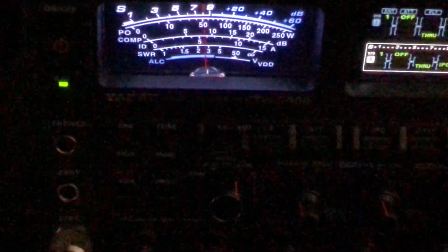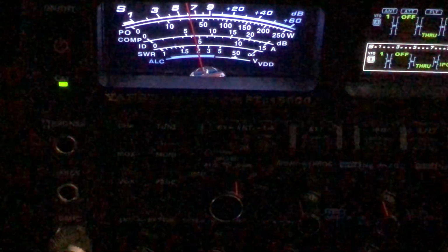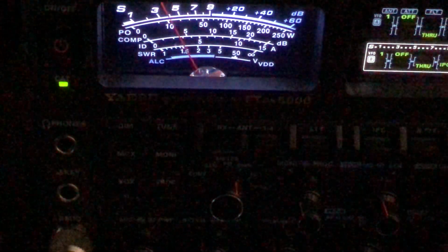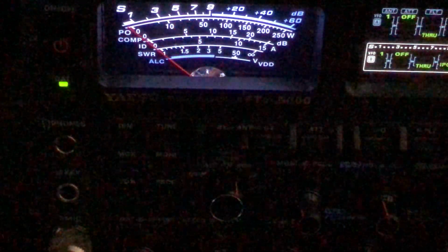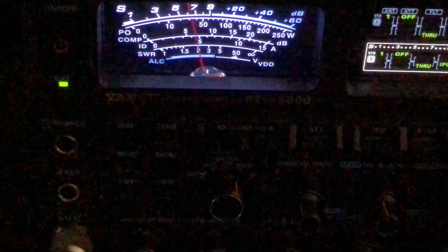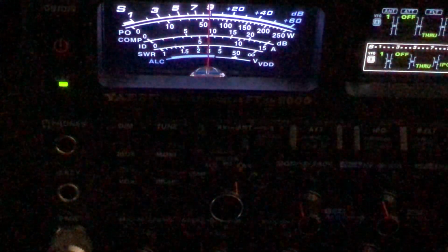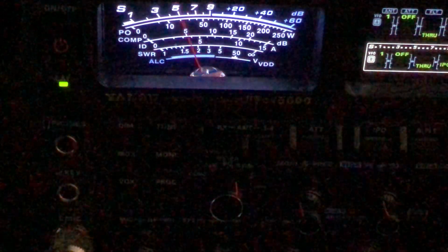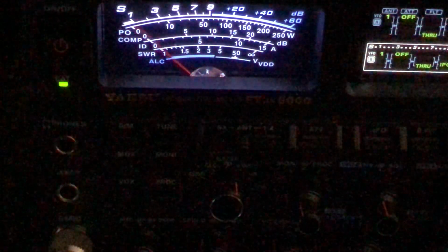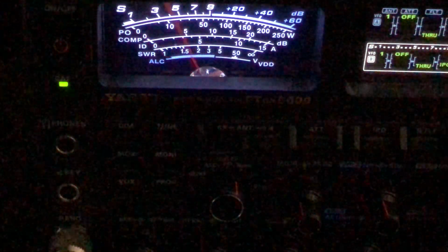Now with CW, this is going to give me the opportunity to explain the last thing I wanted to get into, which is automatic gain control. These S meters, most modern radios, in the past it was different, but most modern radios, the S meter taps off of the automatic gain control circuits. That's way down in the receiver from the front end. And so it's just a voltage they extract from the automatic gain control and use it to drive that meter. So everything you do upstream in the receiver to cut signal strength can affect the S meter.